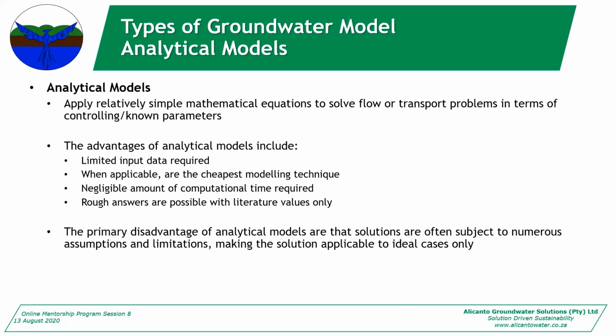A good example of an analytical model that you can apply to most sites is Darcy's law. Just a quick Darcy calculation on your discharge into a box cut or something. It's not going to give you a final answer, but it'll be enough to get you going, to do a sanity check.